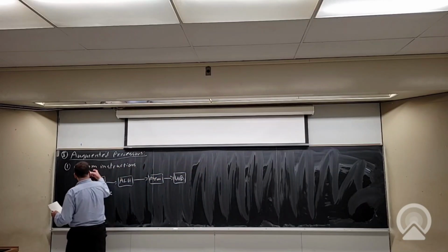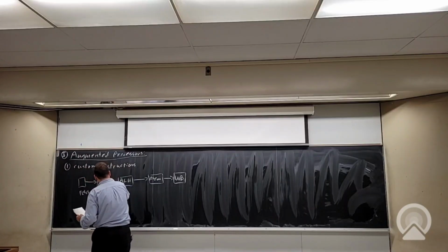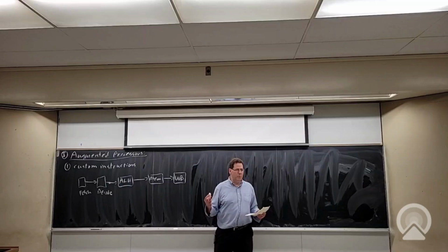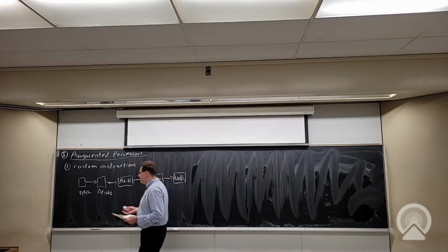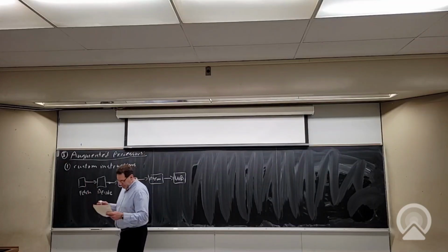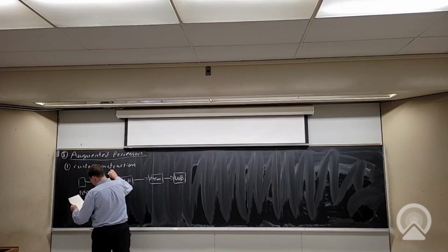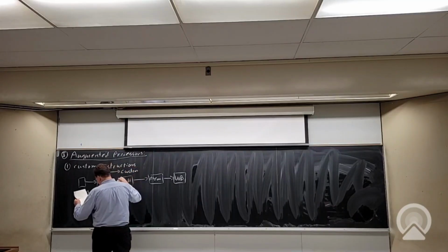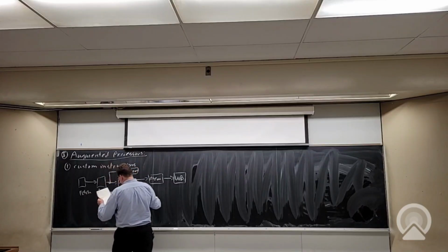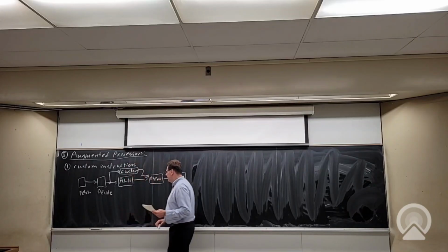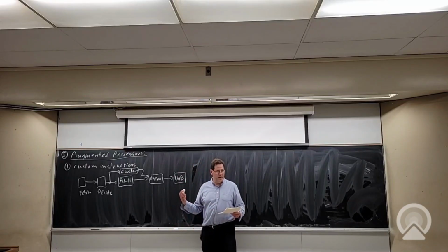Okay, so what these custom instructions do is they reserve some opcodes. Some opcodes they just don't use for normal operations. It's different in the different vendor tool flows, but you can basically go in and say, this opcode maps to a new functional unit that I built. So when you see this, I want the decoder to send it to my custom hardware that I built and put in the FPGA. And it'll do that instead of the regular ALU step, and then it'll normally go into the memory step again. So it basically is like you extended the ALU step of the pipeline.